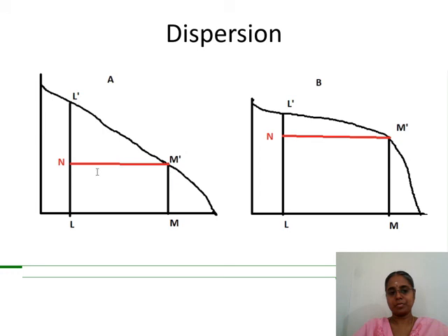So this range, so this many fibers, you can keep common settings for B. Whereas if you keep A, if you use a bunch of fibers, if you keep your length L1 plus 1 or 2 mm as your settings in the draw frame, then all these fibers will go as floating fibers and it may catch any nip and it will cause unevenness in your yarn production.